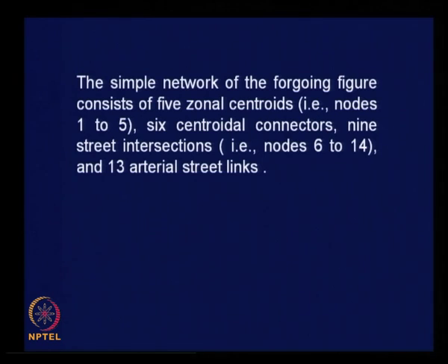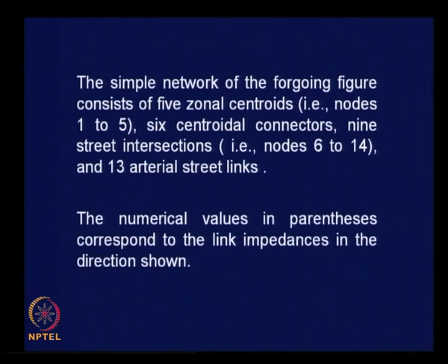Please remember these values because we will be discussing this network frequently to understand a few other aspects related to assignment. The numerical values in parentheses correspond to the link impedances in the direction shown. We generally term it link impedance, but in practice we take it as travel time. Link impedance means a different aspect, it is not simply travel time.